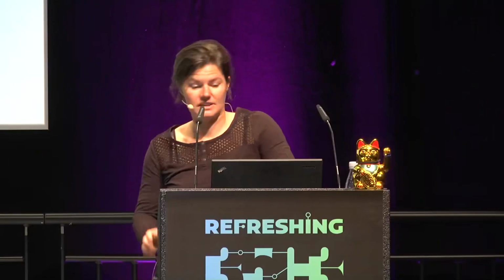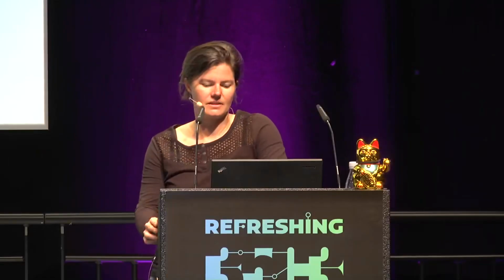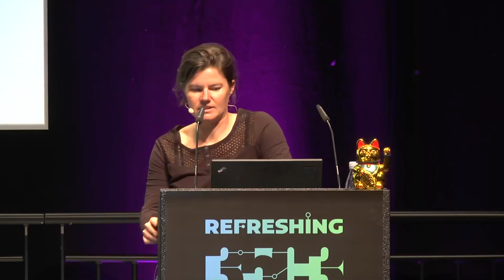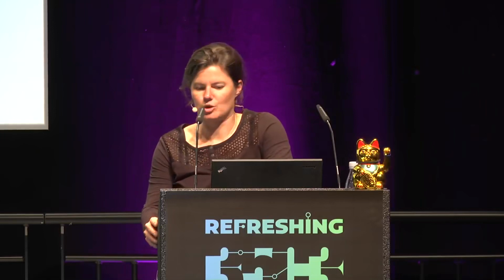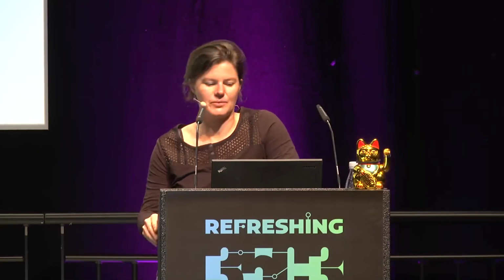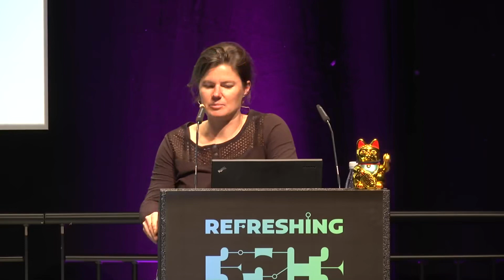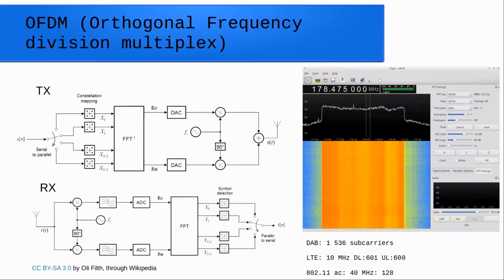Additionally, often there is a guard interval added to the symbol, to cope with more delays. For example, DAB is a broadcasting system with the capability of single frequency networks, so you can run different transmitters on the same frequency with the same program, but especially in the overlapping areas, this results in very large delays.